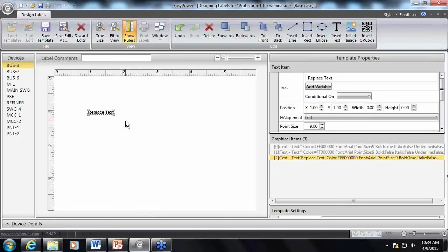At your facility you may have certain ranges of clothing, like maybe 8 calories per centimeter squared is one level, and the next level would be 40 calories per centimeter squared. Or maybe you follow the table H3B in the NFPA 70E, so it's 1.2, 12, and 40, and maybe you don't want the specific energy, but you just want the highest energy for what your clothing is rated for.